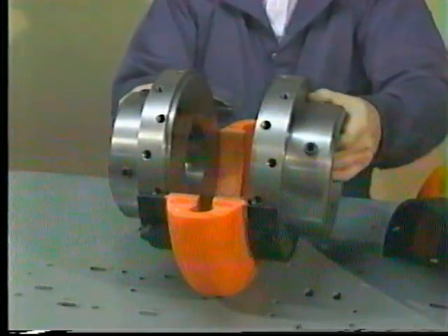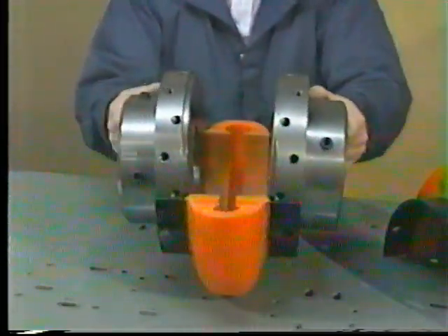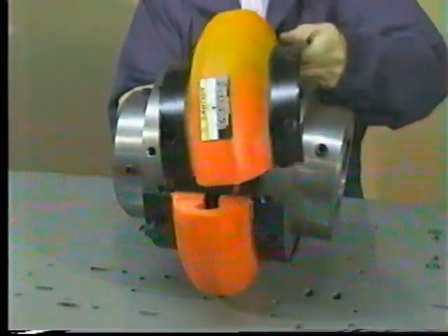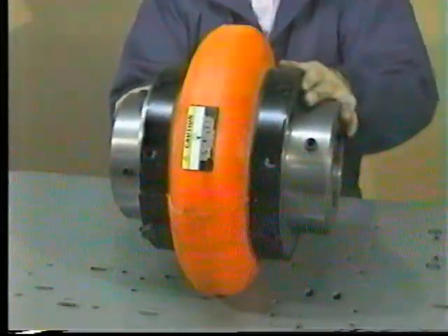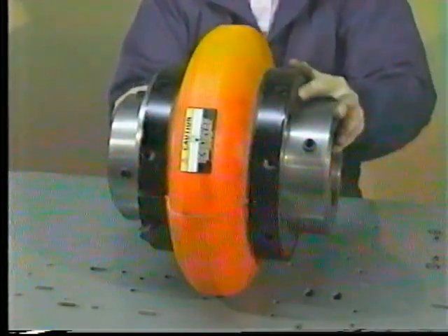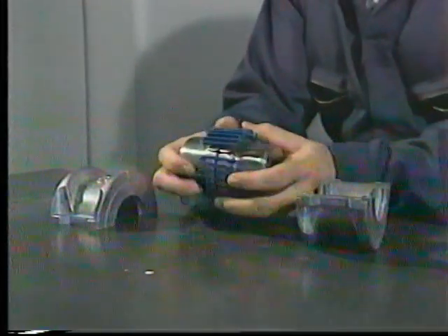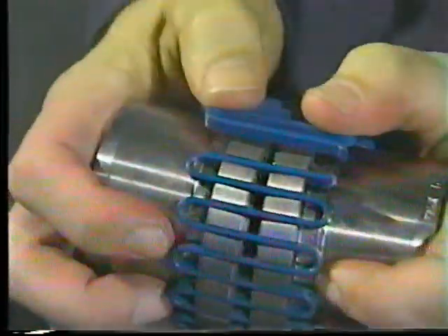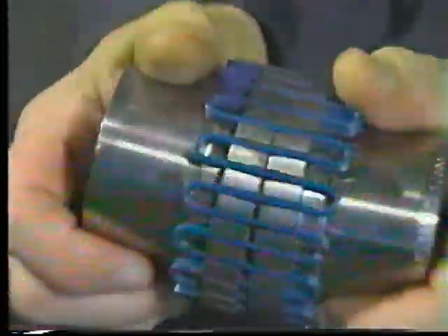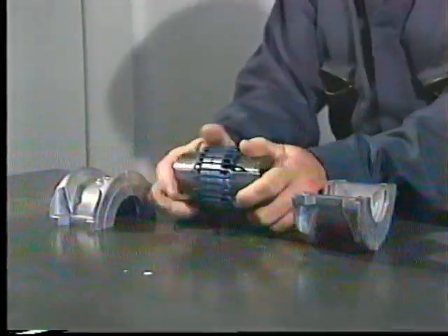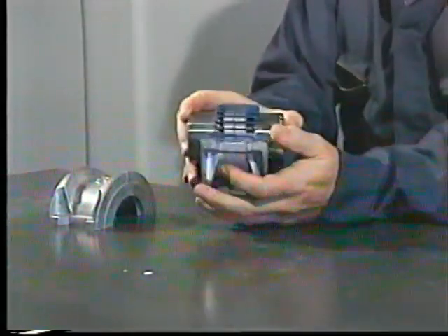Another style of flexible coupling is referred to as a rubber tire coupling. Shafts are connected to both sides of the flexible tire, and all the flexing occurs in the tire itself. Another kind of coupling is the steel grid coupling. Its two halves are connected with a continuous grid of flexible steel which locks around the center of the coupling but still permits it to move. The coupling includes a cover.